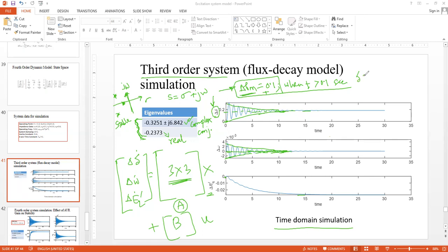So your actual delta value would be, of course, delta naught plus del delta. This is your original value of the actual delta rotor angle variable. If the initial value was, I can't remember, probably 23 point something degrees, plus del delta would be 0.19 degree. Then you have to add it to get the actual value of delta.